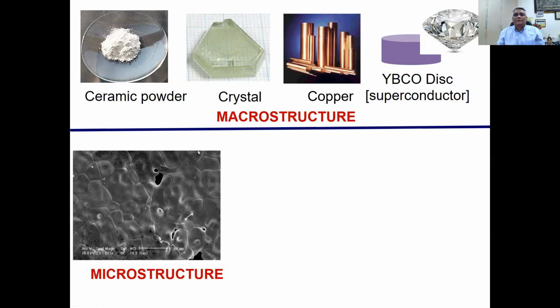I want to measure the dielectric constant, and I can measure it, but at the same time, if you measure the tan delta loss, the dielectric loss will be enormously high here because of these grain boundaries, because the charge that is separated will quickly start leaking through these grain boundaries and voids. So you can't make a capacitor out of it, number one.